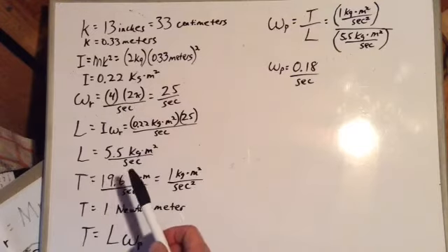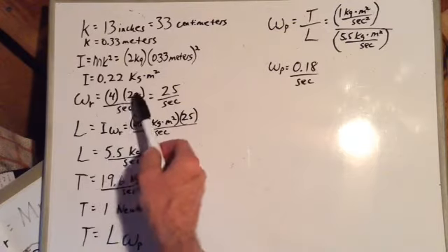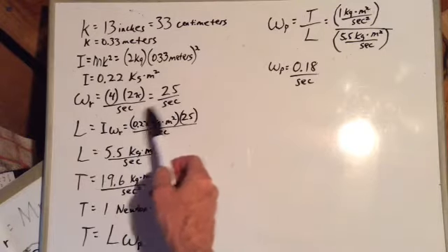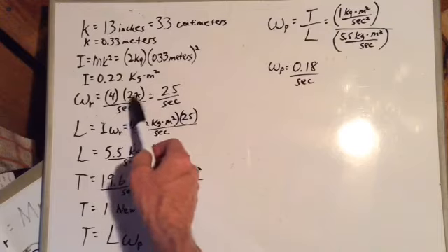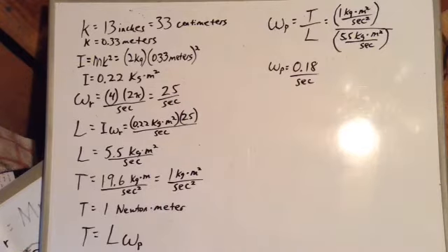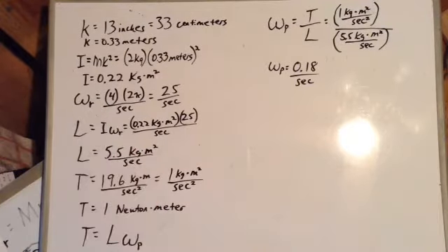Okay, let's say the wheel is spinning 4 revolutions per second. This would be 4 times 2 pi radians per second. So its angular velocity would be 4 times 2 pi per second, which is about 25 radians per second. We use the term omega sub r to denote the rolling rate of our wheel. That's the rate at which the wheel is rotating around its axle.